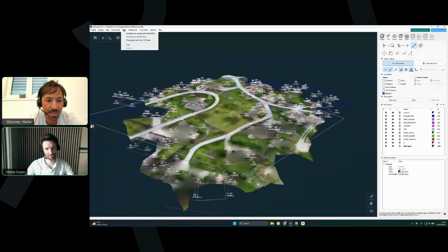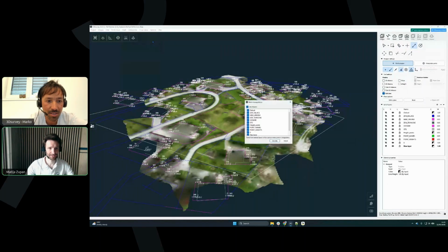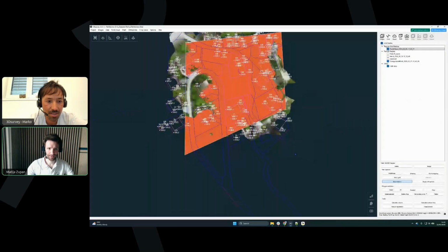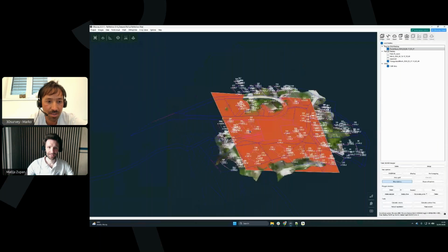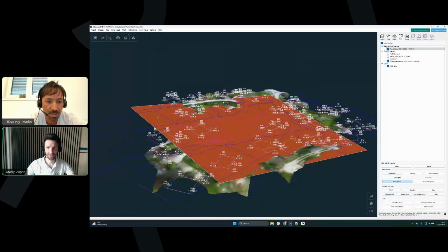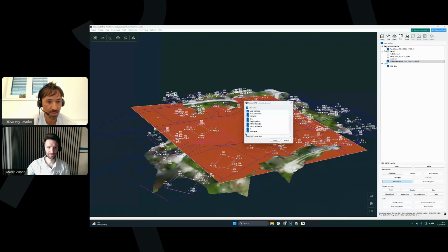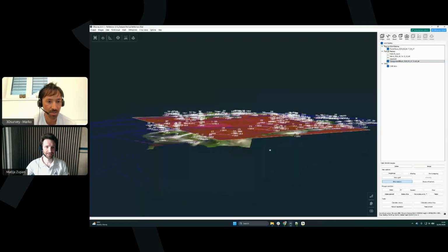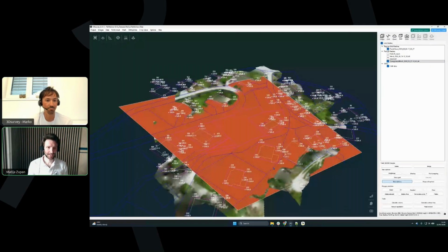And I will create another mesh triangulated from this CAD data. Use my new layer. Okay, so this is my plane on 520. And if for some reason I need all my CAD to be on 520, I will just go here on this new mesh, right click, project CAD to mesh, and select all previous CAD that I've had. And now let's watch closely, project, see everything jumped a little higher. And this is how you can manipulate your CAD data.